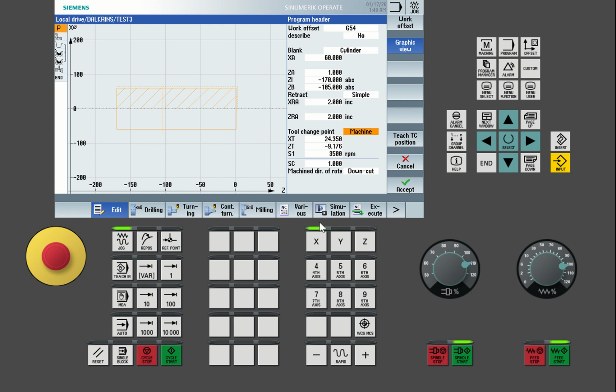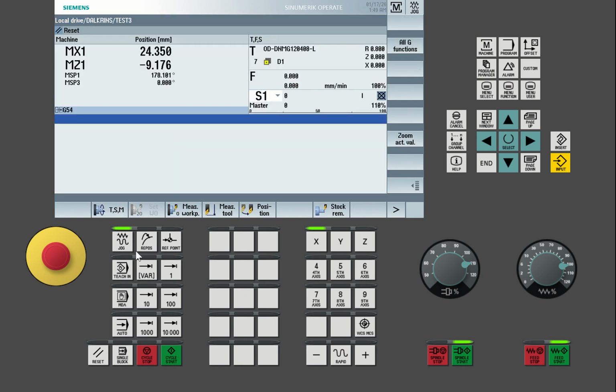So what do I do? For example, I can come to this machine mode, then jog mode, I can click on Z, then I can try as much as possible to move Z away. But remember, this one I cannot control from this side, because I don't have this parameter. Or I can say now home my machine. Let me home the machine first of all, home machine for X. But remember, Siemens doesn't home the machine, and this value is not good.